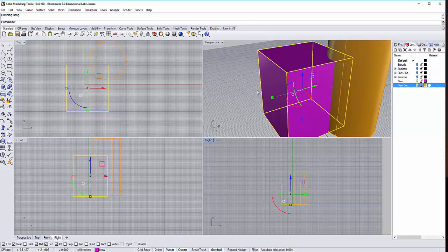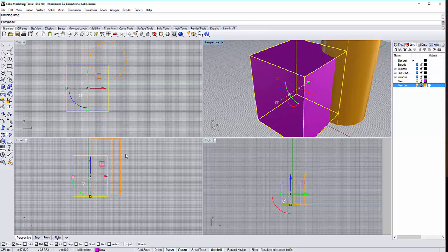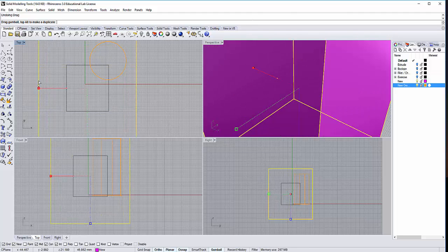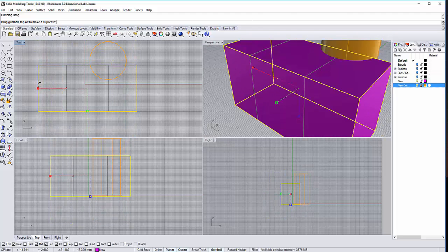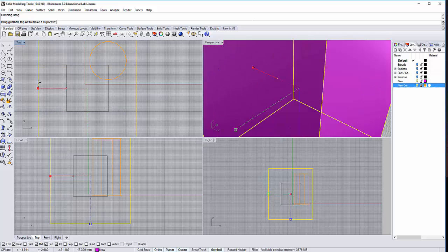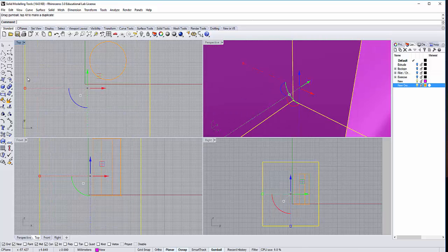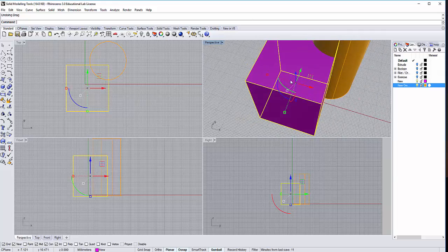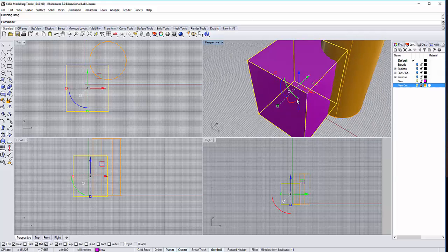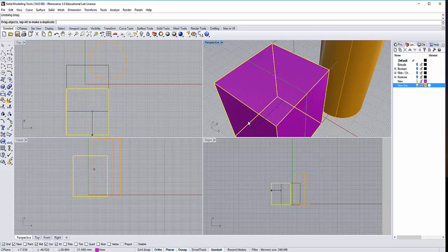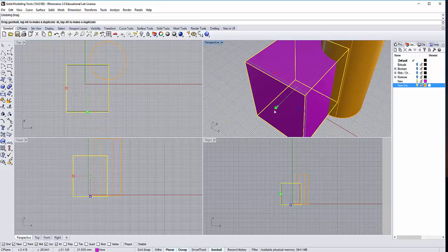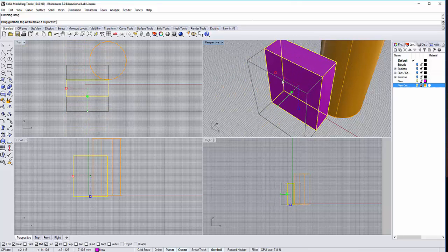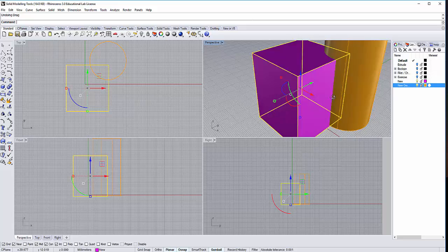What happened? Let's say if I want to scale in two dimensions, okay, I need to press shift. Can you see the difference? Okay. You need to press shift in order for it to scale proportionately, I would say. All right. So try those few buttons. Okay. Let's say for example you want to scale it in one dimension, no proportion. All right.